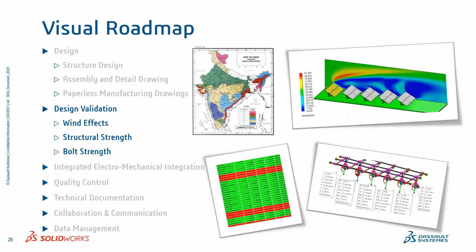Moving further, I'll be taking you through the various functionalities within SolidWorks for validating your solar structure design, because it is very important for any solar structural designer to understand the effects of wind, and thereby the strength of the structures we design. It is also important to understand the strength of the bolts and how much load is coming on each bolt, to decide on the foundation bolts to overcome the effects of this wind load.